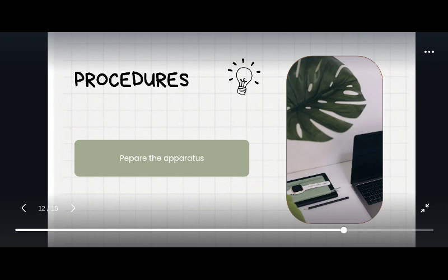Turn the crank of the apparatus at a rate of approximately 2 drops per second and count the number of drops, n, it takes to make the two halves of the soil pad come into contact at the bottom of the groove along a distance of 13 mm, half an inch. If the number of drops exceeds 50, then go directly to step 8 and do not record the number of drops. Otherwise, record the number of drops on the data sheet.